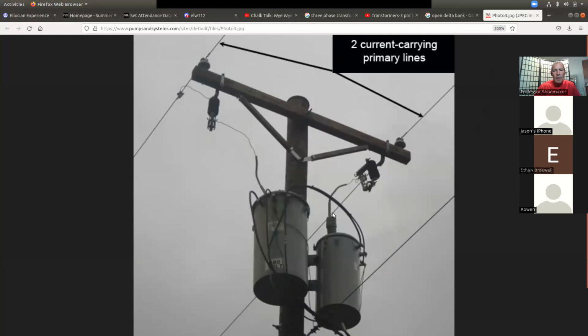It's the only one like it. If you'll notice, which transformer is my lighting transformer, left or right? Left. And my right one is my high leg transformer. This transformer, I've got two hot legs and a neutral so I can power my house with it, plus the tie-in bus that goes across. They do a little squirrely thing right here. Then out of this far side, which is hard to see in your picture, I have my high leg. So that just shows you what it is in the real world.